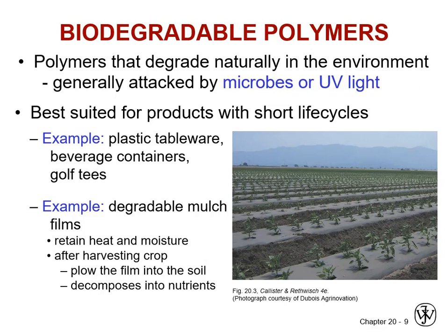So when we look at adding things like UV inhibitors and fillers and other protectives into our plastics so that they can survive weathering, something to consider is don't make them too robust. Make them robust enough to survive their service life, and then beyond that point, weathering and degradation by UV and other surface environment aspects is a good thing.